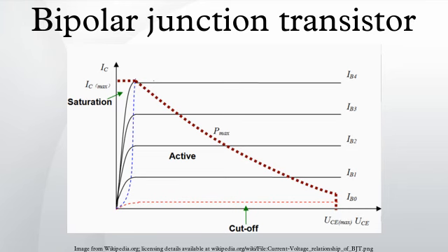In typical operation, the base-emitter junction is forward biased, which means that the p-doped side of the junction is at a more positive potential than the n-doped side, and the base-collector junction is reverse biased. In an NPN transistor, when positive bias is applied to the base-emitter junction, the equilibrium is disturbed between the thermally generated carriers and the repelling electric field of the n-doped emitter depletion region.